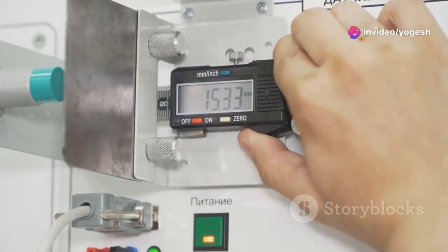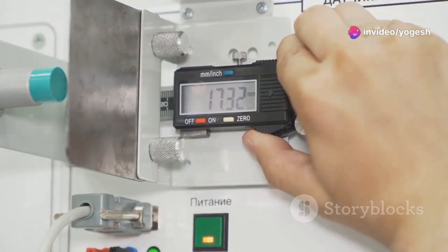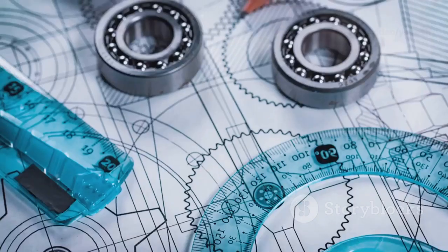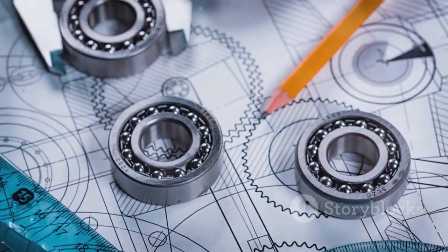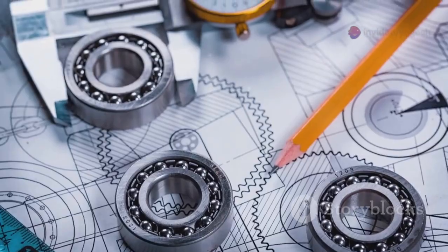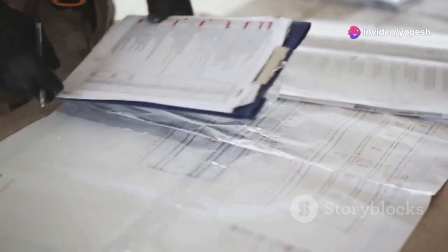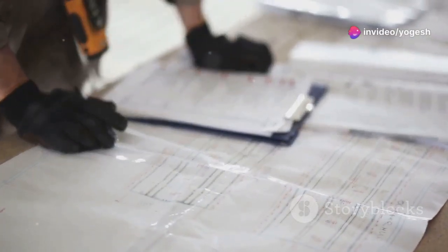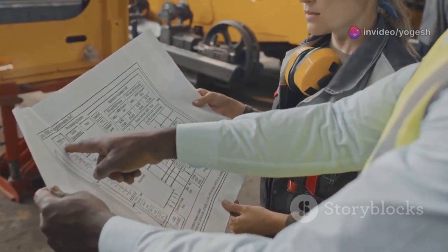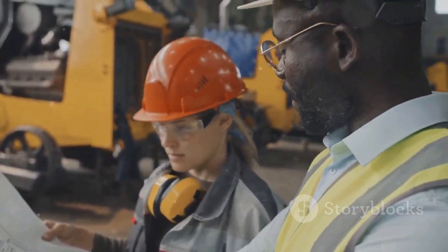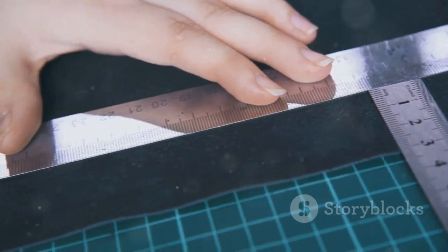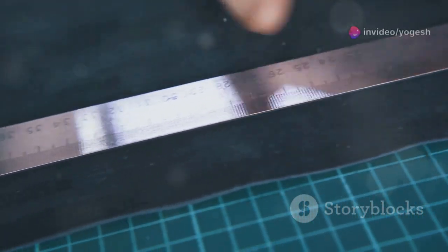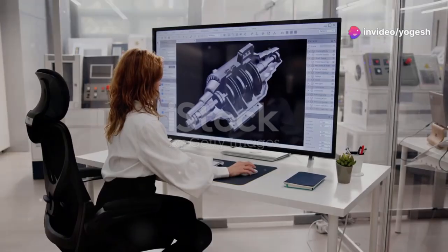Next, apply realistic manufacturing tolerances. No process is perfect. Standard tolerances are plus or minus 0.25 mm for dimensions and plus or minus 1 degree for bends. Only use tight tolerances where absolutely necessary. They increase cost. Discuss tolerances with your fabricator to match their capabilities. Careful flat pattern checks and smart tolerancing make your designs manufacturable and affordable.